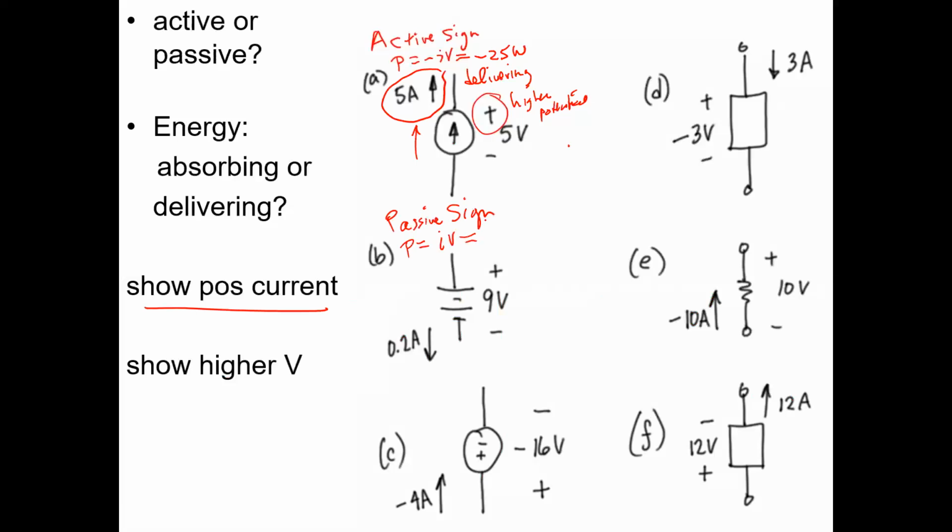And in this case, that equals, power is going to be, was that 1.8? Something like 1.8 watts, right? Is it absorbing or delivering power? Absorbing. So that is a symbol of a battery. When do batteries absorb power? When you're getting them charged. Yeah. When you hook up your phone to the charger at night, it's absorbing power. Current flowing into the high energy side, building up energy in there, right? So it is absorbing. The direction of positive current is down, and the higher energy side is